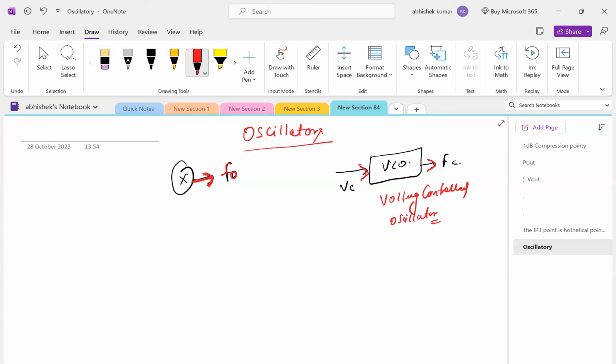And in our wireless devices, this oscillator is very much used. Why is it very much used? Because our voltages are not constant at every point of time. Because of the noises, the voltages change every time. So we need to have a different frequency depending upon the voltages being fed to the system. So that is the voltage control oscillator that changes frequencies depending upon the value of the control voltage input. They are used in transmitters and receivers, and that is the theory part.